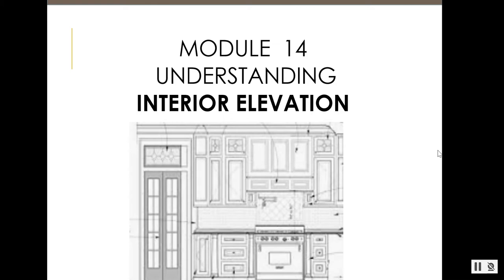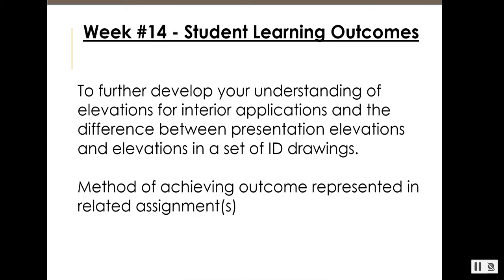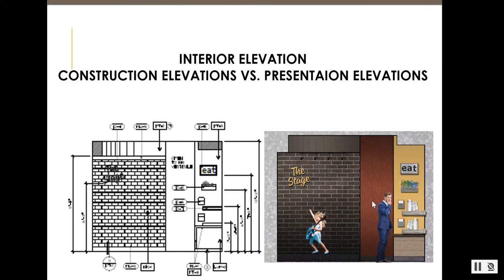more in detail. So this week we want to further understand elevations for interior applications, the difference between presentation elevations and elevations for a set of ID drawings, interior design drawings. And these are the methods for these outcomes represented in this related assignment. This is how we'll achieve these methods. But I want you to understand in this lecture the difference between presentation elevations and ID drawings. That's interior design drawings. That is what we are doing.